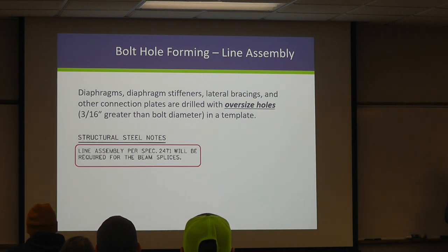For our field splices in a line assembly, they're going to be drilled with a standard size hole. The standard size hole is a 1/16 of an inch larger. I know that doesn't seem like a lot, but when you're in the field, that's a lot of wiggle room. That's 1/16 versus 3/16, right? So this is important to understand because you can start to appreciate what some of these tolerances are, especially as I show you some more pictures.